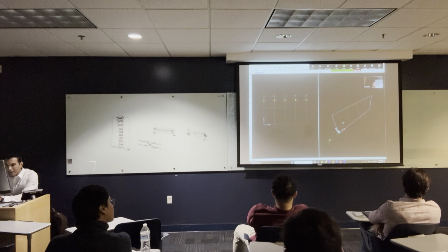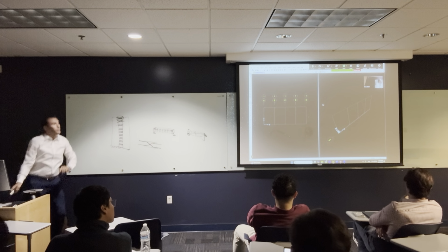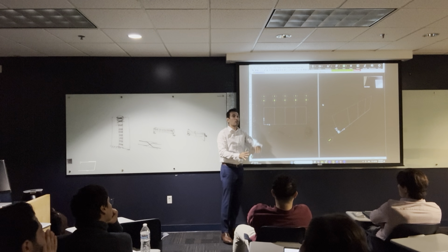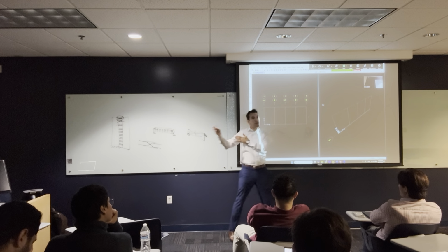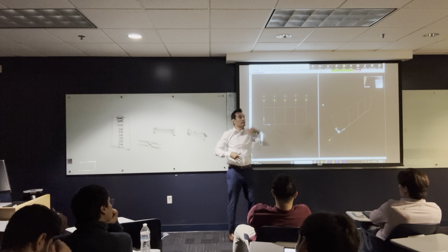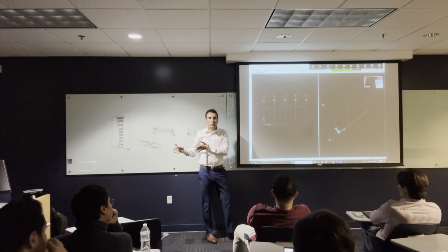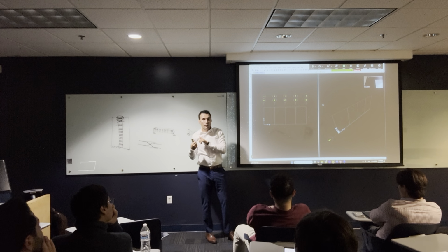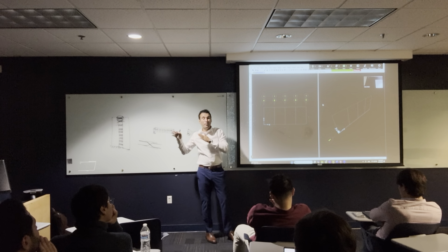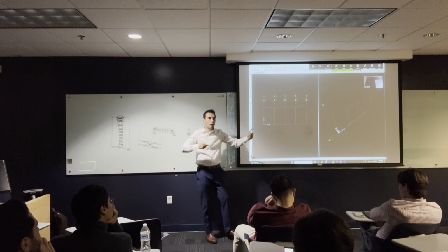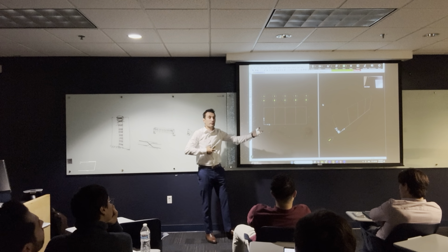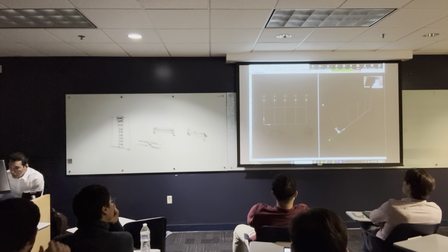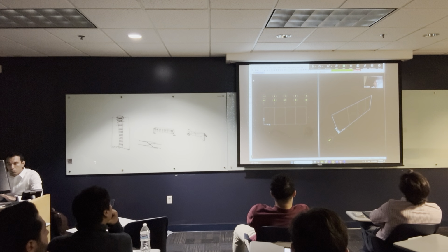And then I'm going to say okay. Right now I defined all the load patterns that I have. So I'm ready to start drawing the structure because I already defined the sections, and I'm ready to assign the load on the structure because I already defined the load patterns. Okay? I couldn't do this in the first place without defining all these systems. I can do them later, but it's going to cost me a lot of time down the road to define these things again. All right, so let's see what we can do next. Next is to draw the structure. You can draw the structure using multiple things here.